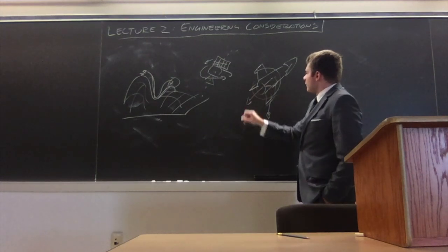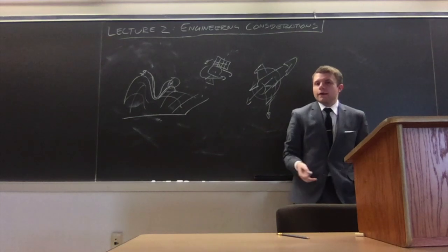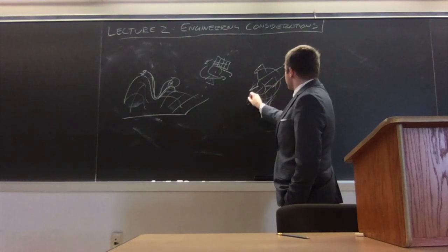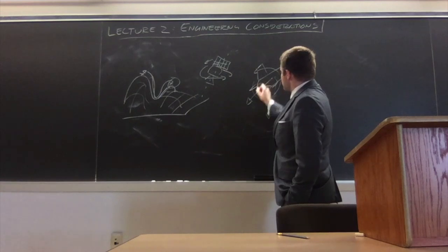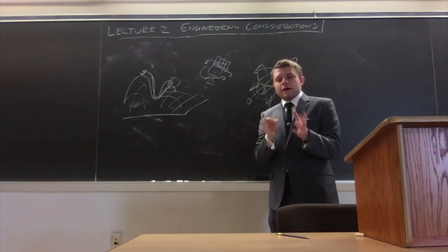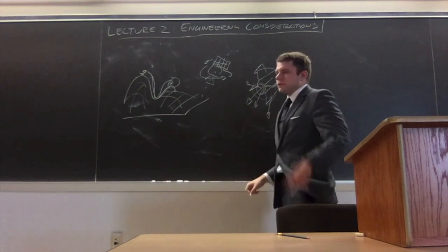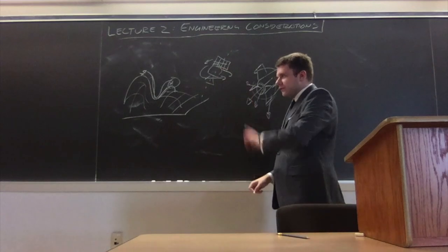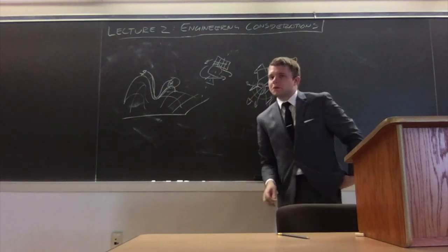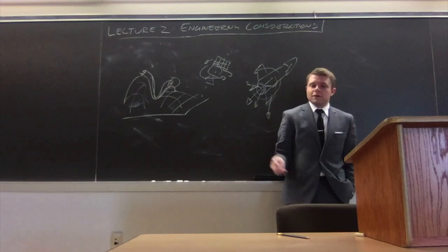Same with the motor, too. Not all engines burn symmetrically. And that's completely okay. You have to make the consideration that the engine may have little asymmetries in how the motor is running, and you have to plan for that. And by spinning it, you average out that error across a much larger area, partially self-cancels, and that means you can have a much straighter and much more simulation-accurate flight. And that's a really nice and convenient thing.